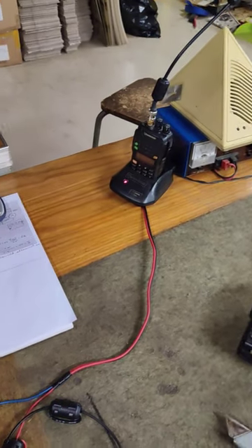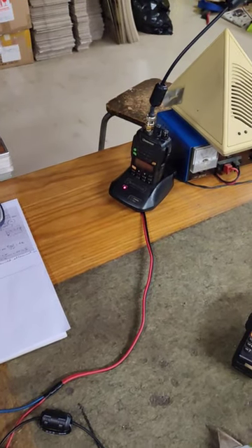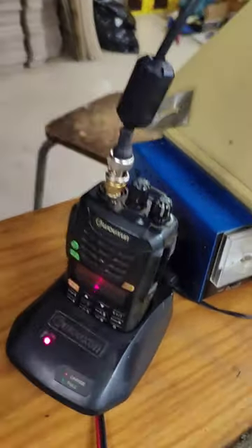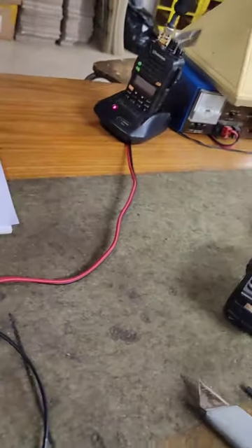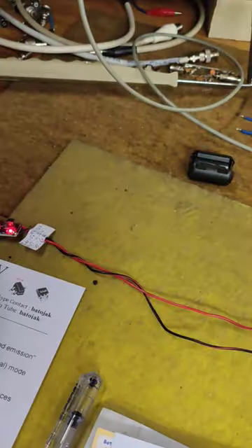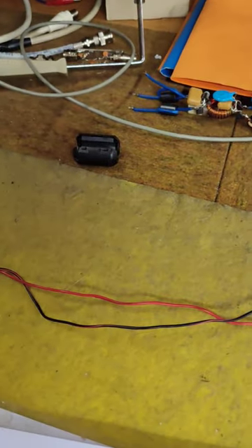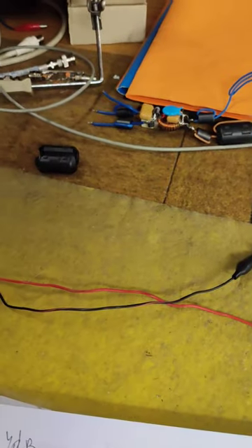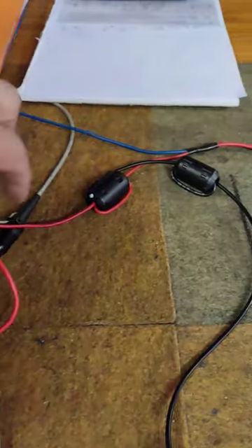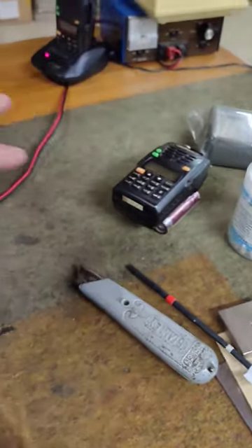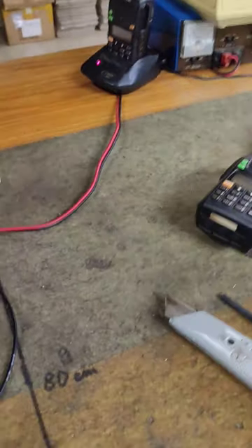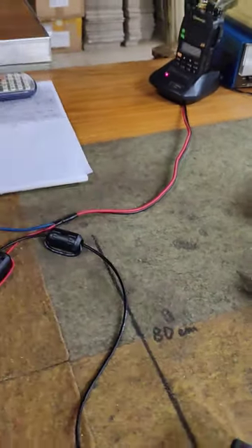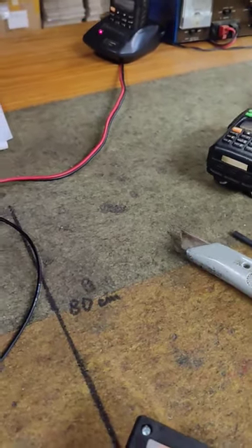Now I'm going to connect it up direct, no filter. Listen to it. The sound will disappear. You can actually see, it's totally disappeared. The actual voice, you just hear basically white noise. And that is the actual signal radiated, also with these wires, without the filter. It's flowing through the wires, and because it's connected to the power supply, it radiates all over the show. And of course, my antenna on the radio picks it up, and it just blanks out the sound.